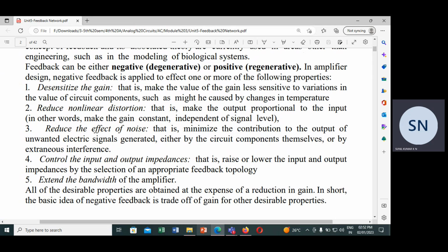And that corresponds to the upper cutoff frequency. That is what the bandwidth is. So bandwidth is nothing but fH minus fL. The higher the bandwidth, the better the frequency response of the amplifier. So we have to see that the bandwidth is very large. That means for any signal frequency of our interest, we should get maximum gain, because from this frequency to this frequency you are going to get maximum gain. That is what is expected for any amplifier.